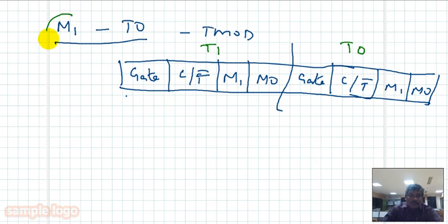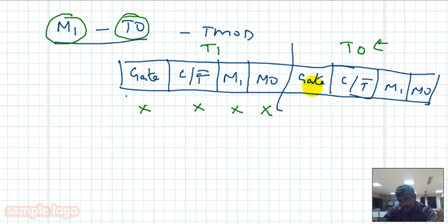In the question, you are asked to use timer 0 in mode 1. So timer 1 is not required. So the value of timer 1 is don't care. And we are going to use timer 0. In timer 0, what is the role of the gate bit? If the gate bit is 0, using instruction you can start the timer. If the gate bit is 1, along with instruction you need to apply some external pulse. But here in the question, no such cases are given.